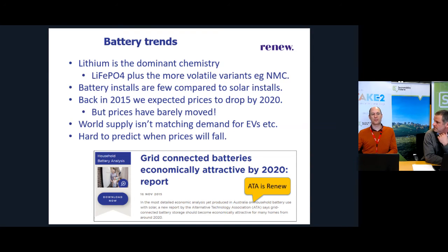It's where you'll still pay something for the energy that you're using, like per kilowatt hour, but some of the cost of your bill has moved into a charge per kilowatt of power, of instantaneous demand. So if, for example, your main load is air conditioning, and you have a heat wave in January which spikes up your demand at say 7 p.m. at night, then your retailer will record what that level of demand was in kilowatts, and they'll base part of your bill off that number into the future for maybe the next year or so.